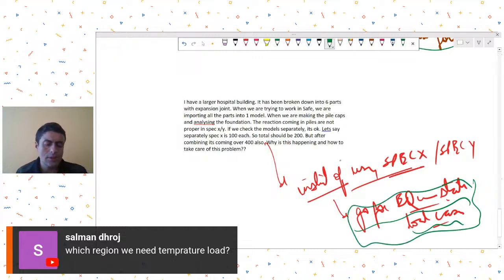Because the base shears are not scaled, the base shear for response spectrum load cases usually comes out lesser than the base shear for equivalent static. So my suggestion would be, for raft design, you go ahead with equivalent static.